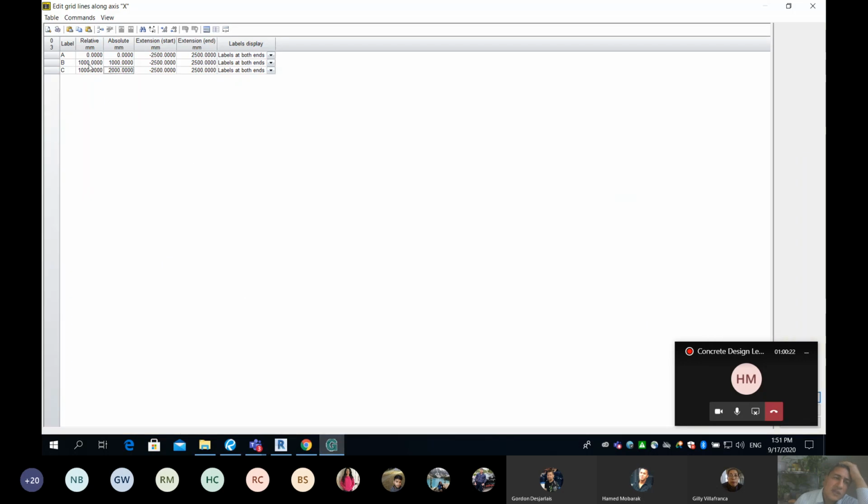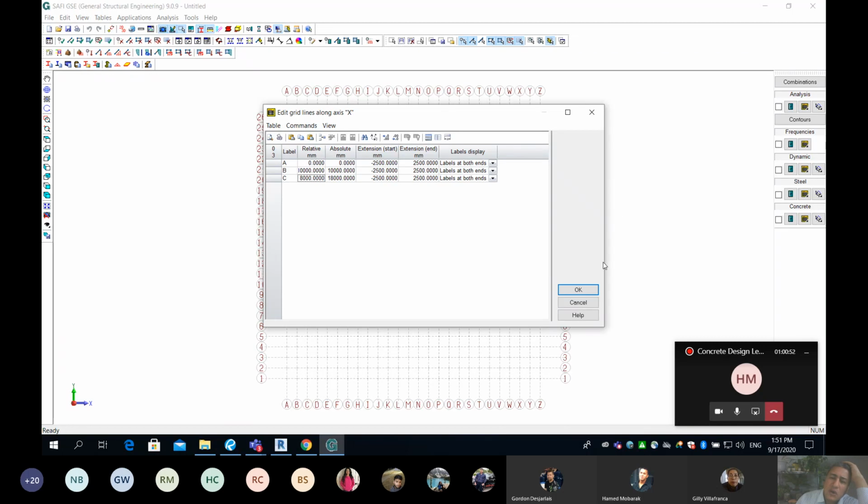So what I have to do is double click here, and you can see right now it's 1,000. I'm going to edit this one to 10,000. And remember, what are the units? It's here, relative, and it's in millimeter. The next one, I double click here, and then I write here 8,000. What does it mean? You're telling the software between A and B, make it 10,000. Between B and C, relative, make it 8,000. And by the way, we are done. All you have to do is come back here and hit OK.